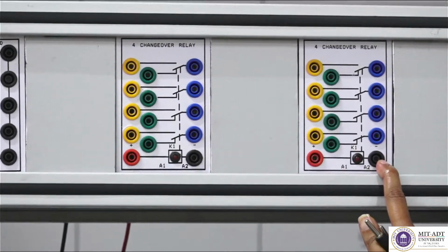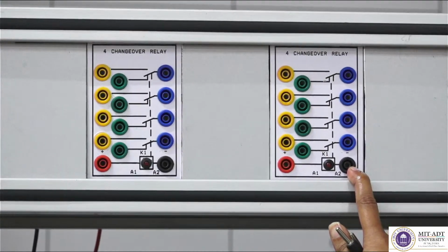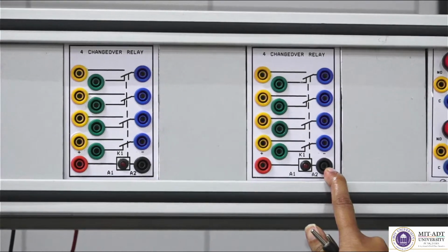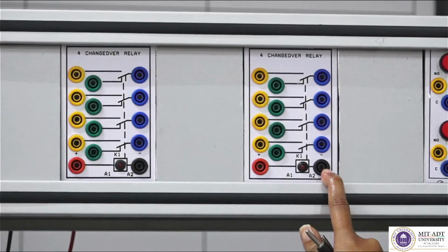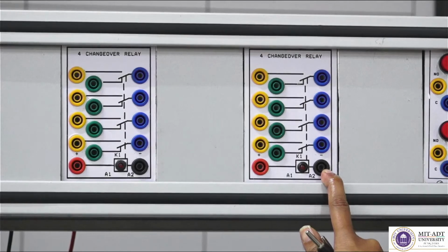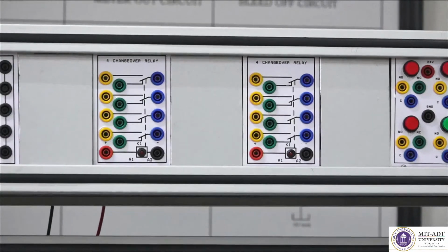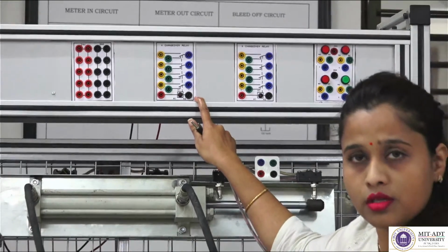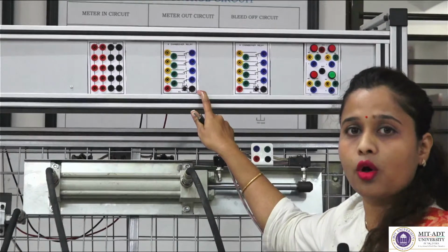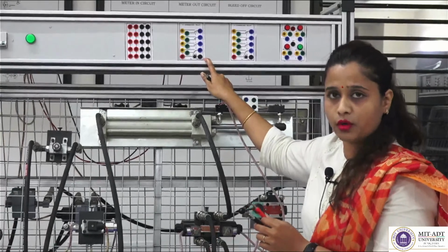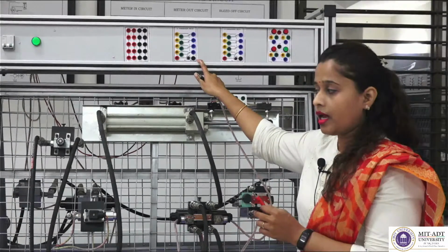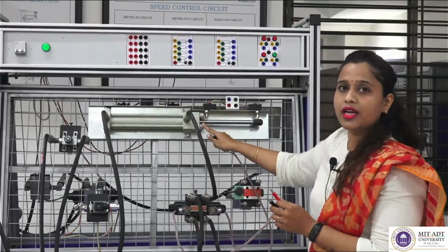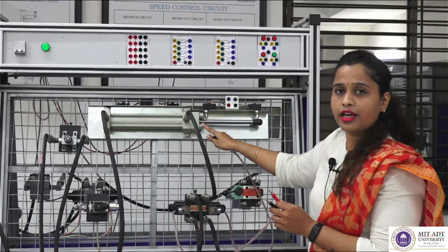So, I am making use of the relays in order to switch different positions of the DCV with the help of solenoids. I use normally closed as well as normally open contacts with the help of solenoids, and then I operate the extension stroke as well as the retraction stroke of my cylinder.